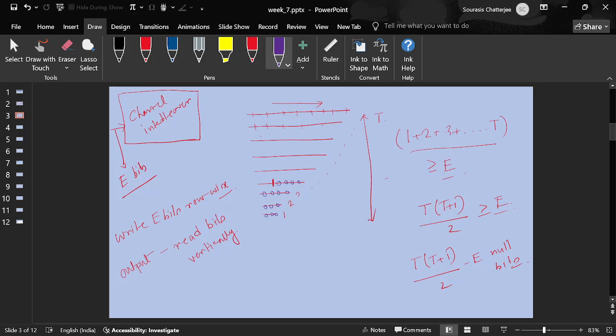Concatenation in what sense? We have done segmentation, right? In UCI there is a possibility there will be maybe one block, maybe two blocks. If this UCI length satisfies the criteria we mentioned in the previous slide, we will segment it and we will have two blocks. Then we perform encoding, rate matching and channel interleaving in a blockwise manner.